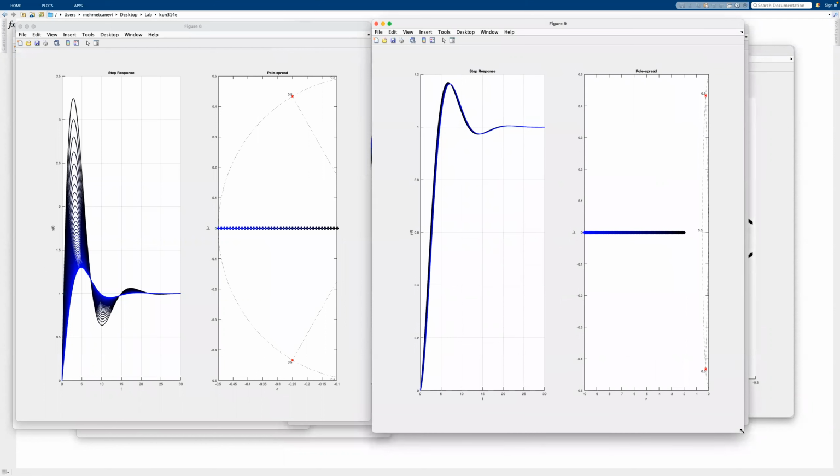Now what we see here is that in case of adding a 0 in the dominant region, in the vicinity of our pole pair, is a bit more dangerous than adding a pole, because at least the pole was dominating for some portion, and we had 0 overshoot, and then it just changed the system behavior, but it didn't surpass the overshoot of the pole pair.